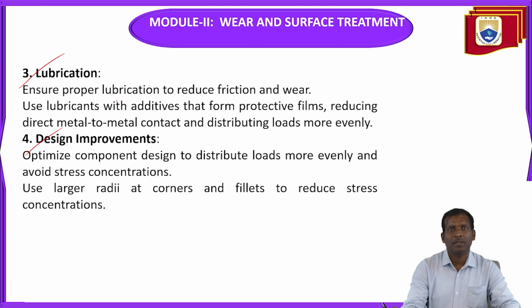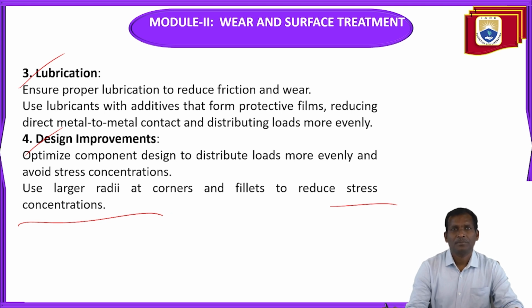Next, design improvements. Optimize component design to distribute loads more evenly and avoid stress concentrations. Use large radii at corners and fillets to reduce stress concentration. The stress concentration is very important when designing the components.